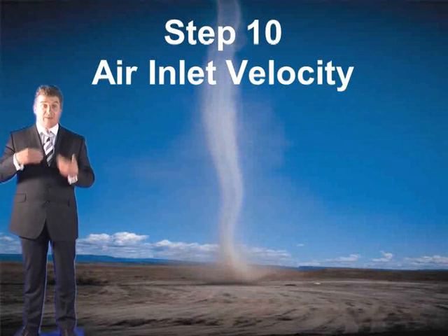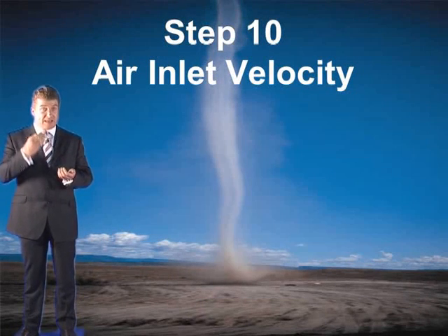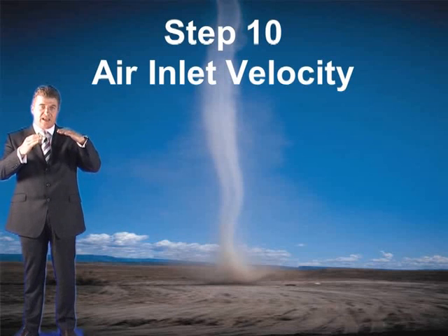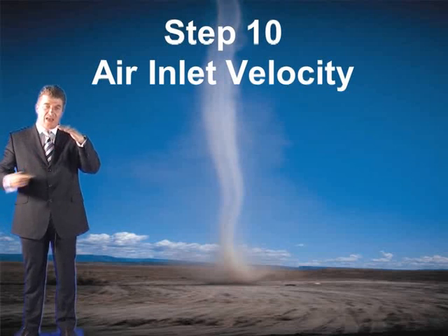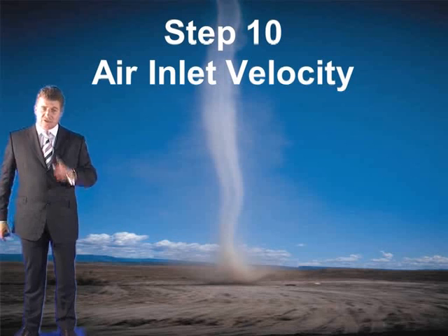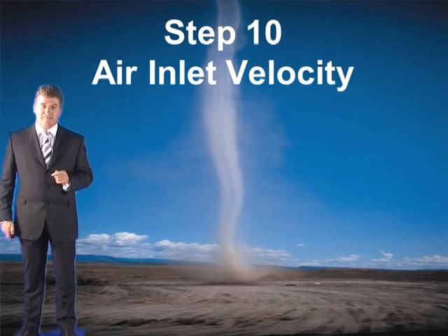Let's move on to step 10, which is the air inlet check. Now, the air inlet check only applies really to mechanical ventilation, not to natural. You're never going to get a system where the natural ventilation is drawing in that much air that it's going to cause a problem with the means of escape, the velocity. So in this case, you don't have to carry this check out because it's a natural system.